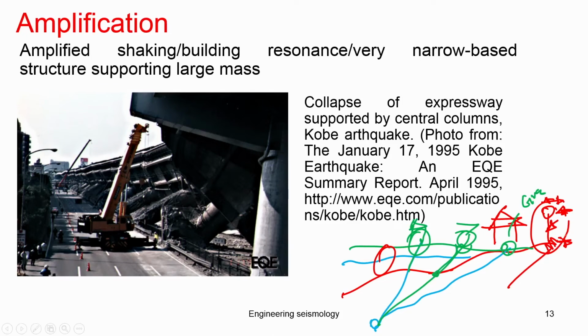So, those who are sitting in a seismically active area, or people who have experienced earthquakes. If you are living in apartments which are relatively tall, people living in the basement or the ground floor will experience less vibration than people living on the 10th or 12th story, because of this mass imbalance and the shaking level created by the vibration, or the amplification effect of the waves due to the structural system. That kind of thing is also called amplification. This is a typical case caused by such amplification, where the bridge collapsed. Okay. So, this is the typical case.